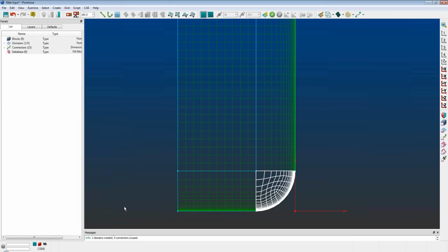For the full mesh, it really only took me about 5 minutes to convert the pole blocks in the fillets to OH on both the IGB and the rotor. And actually I have a version of the mesh saved prior to the conversion of the pole blocks to the OH style. I did this because it's easier for me to modify my near wall spacings later if I want to refine or coarsen the mesh near the walls, and then I can quickly convert them to OH. I'd probably even write a script to automate it for me if I was going to use these kinds of grids a lot.